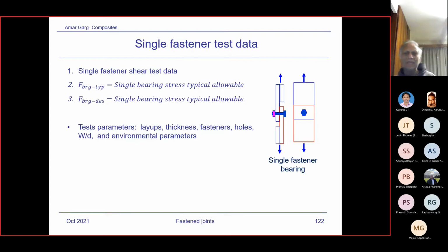So again, the bottom line is you have to really look into the physics. You cannot blindly accept what FEM churns out. So when there is a doubt, you discuss it, consider the hand calculation, try to look into all the parameters, and then accept the results or reject them.